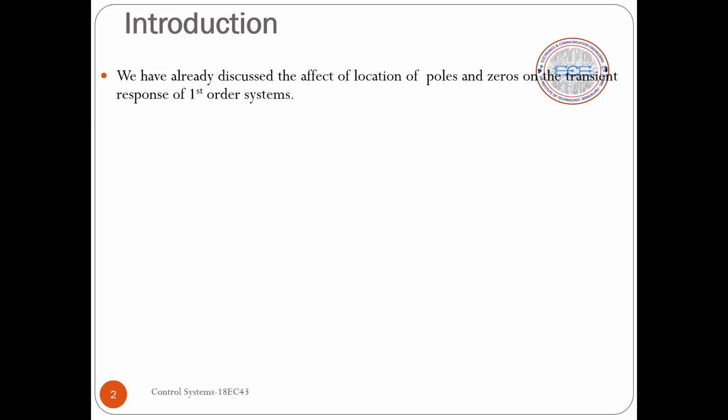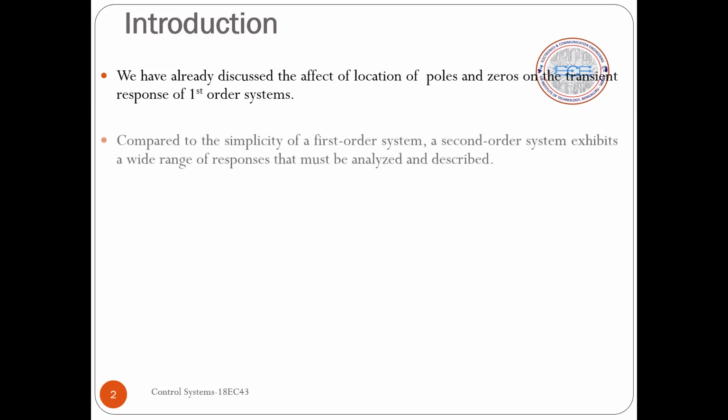If we add a delay element, how the response will change. And by changing the capital K, that is the DC gain of the system, and the capital T, that is the time constant of the system, how the response changes. All those things we have studied for the first order. We found that if the mathematical model is available, then it is very easy for us to find the time response. Otherwise, finding a transfer function itself is a tedious job.